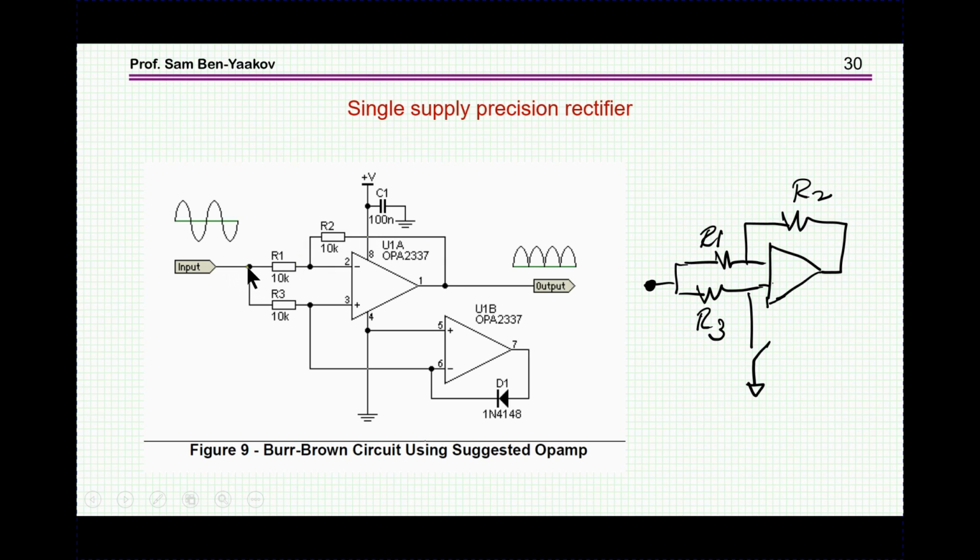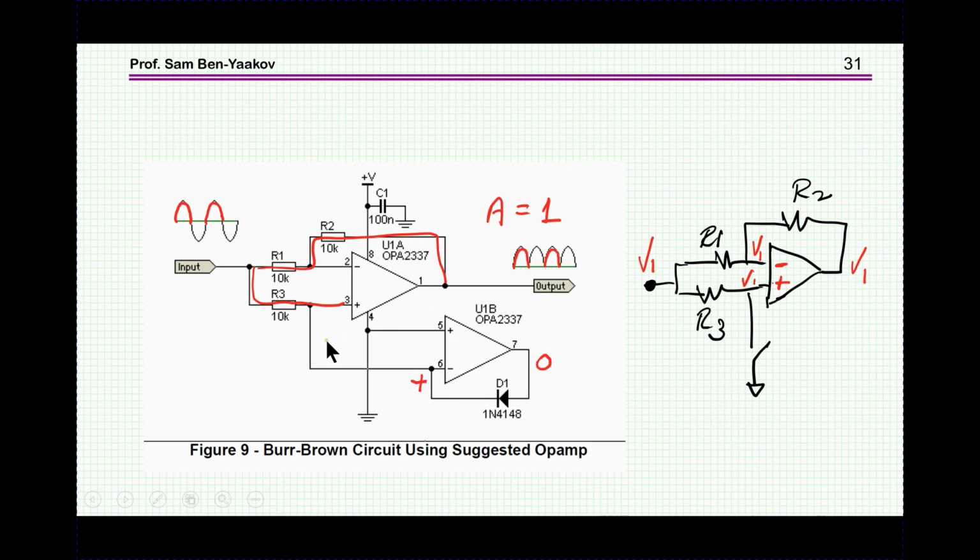It's an inverting amplifier section here. And then we have another resistor which goes into this adder amplifier, which I'll show in a minute. So the idea is the following. When you have a positive input, here is a positive input, this is positive here, and due to the diode, there is no path for the current. So no current can pass here in this direction.